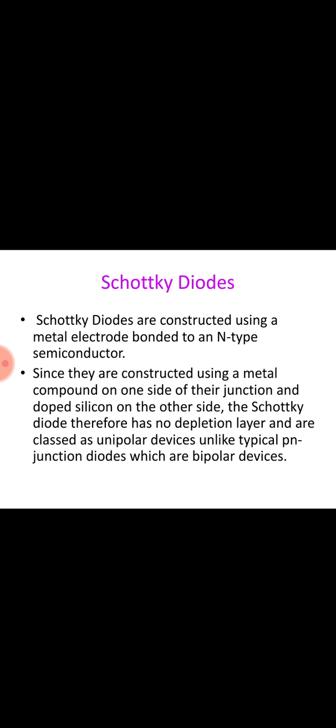We know that a diode is a two-terminal semiconductor device having a nonlinear VI relationship. This nonlinearity can be exploited for the useful functions of signal detection, demodulation, switching, frequency multiplication, and oscillation. RF and microwave diodes can be packaged as axial or beam lead components, or surface mountable chips, or be monolithically integrated with other components on a single semiconductor substrate.